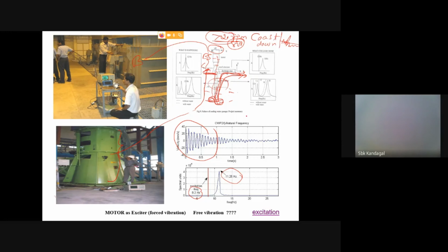Otherwise, you can take a small cantilever beam and do the lab, but such things cannot be expected in these large structures. So what we have done is use the crane hooks just to give a pulse, like an impulse hammer. But an impulse hammer has a force transducer, and this doesn't have one. But the amount of energy the hook delivers is quite good enough to excite the structure. So I'll just show you the video of how it excites the system.